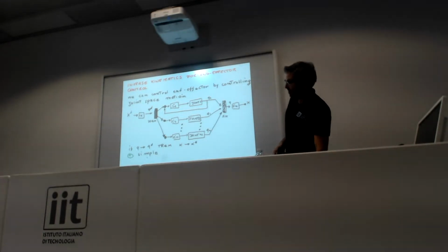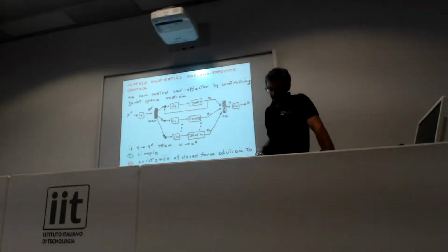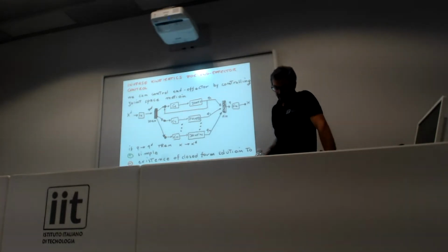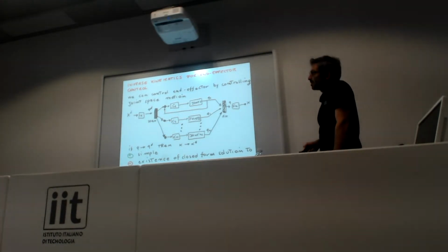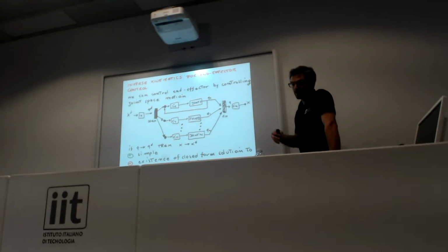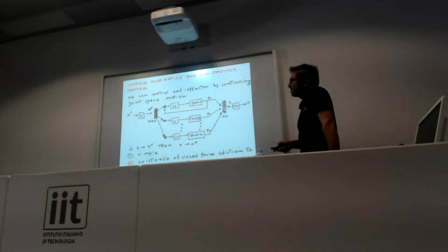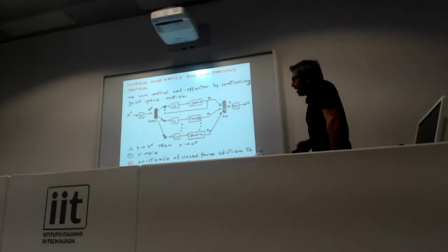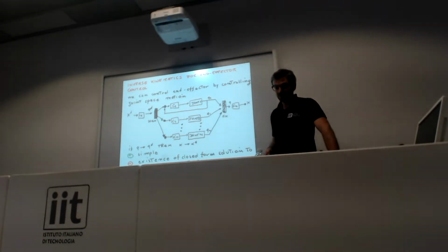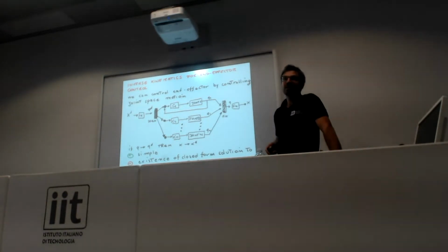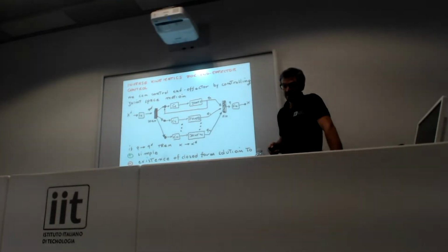This approach is very simple, however it requires inverse kinematics. And inverse kinematics is not like forward kinematics, which always exists and has a closed analytical solution; in inverse kinematics a solution is not guaranteed. What you can always do is a numerical implementation of inverse kinematics that, on the other hand, involves an optimization inside, and so it can be slow.